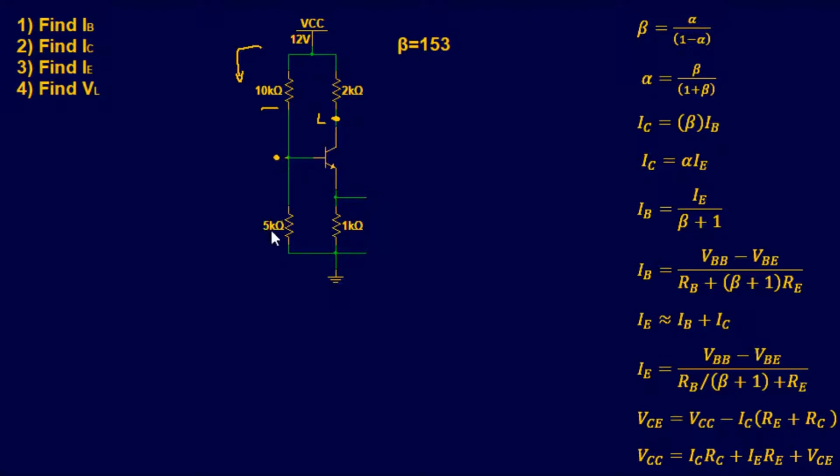So that means there's going to be voltage right there, and then another voltage drop, because current is flowing this direction. Which means our base current is going this direction. That's our IB. However, we've got to find what that is. And I told you in the slides that we can use Thevenin theorem or any other circuit analysis you would like to use. To let you know how to do a Thevenin theorem for this particular circuit, it's not very difficult.